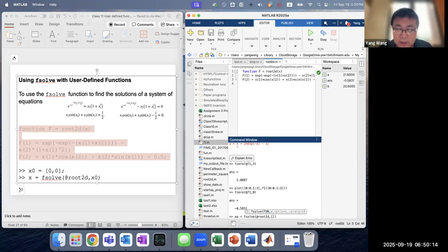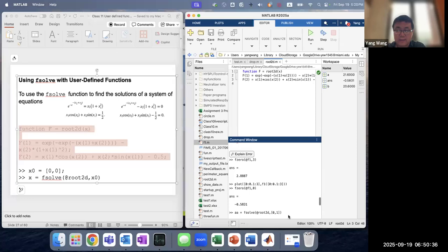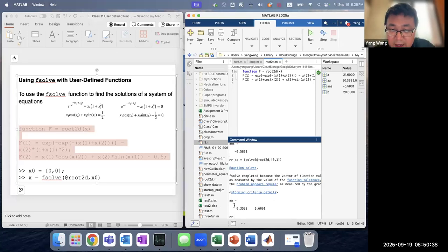And the initial guess, we can give whatever we want, right? So let's just give it a 0 and 0, or 0 and 1. It doesn't really matter, but try not to give something crazy. If you give the initial guess to be really, really far away from the actual result, then it could be that it takes a longer time to eventually find the actual result. So then you can type in, and basically this is AA, right? X1 equals 0.35, X2 equals 0.6.